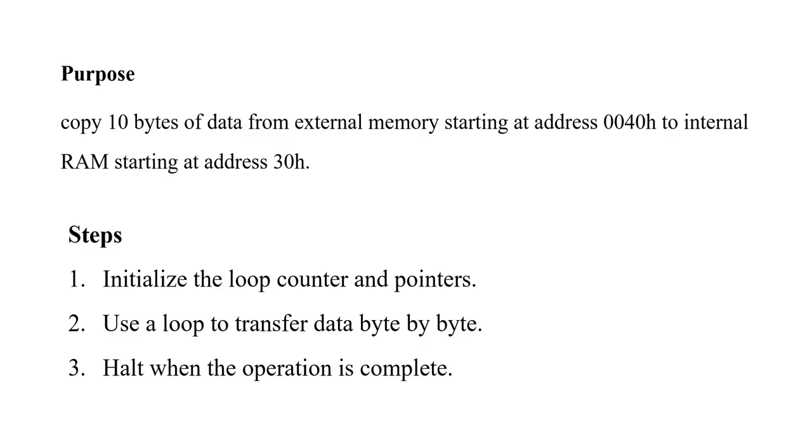And when you write 0040H, you are explicitly specifying the full 16-bit address, rather than writing just 40. That is, instead of writing 0040H, if we write only 40H, it would imply an 8-bit address, which is insufficient for external memory operations, and the assembler would interpret this as an incomplete address and could result in an error or unintended behavior.